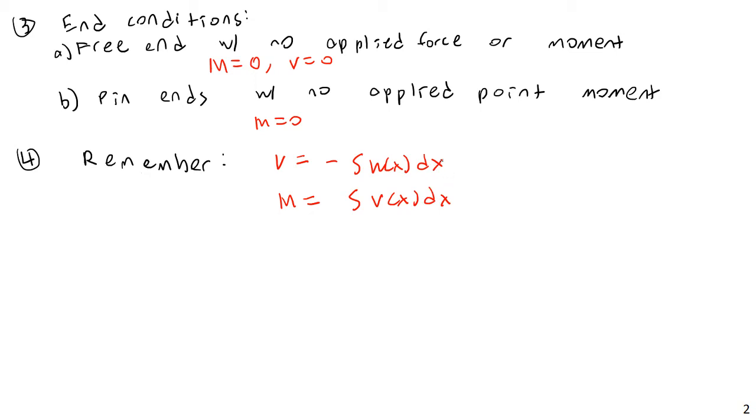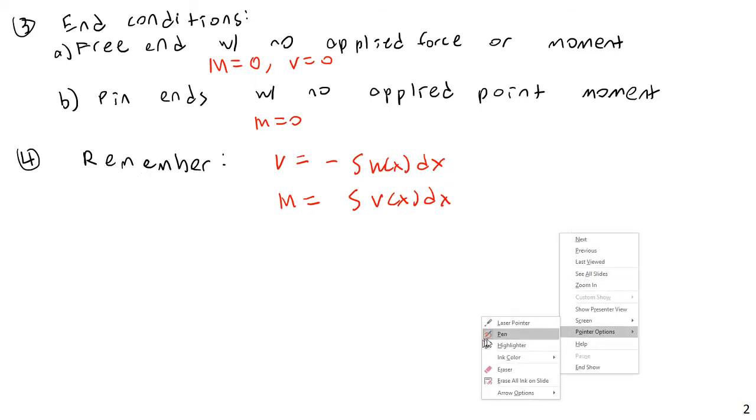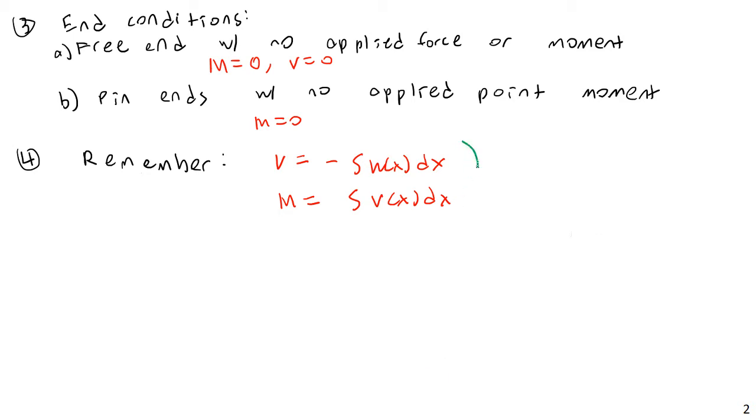Or in other words, what are these? What is an integral? Obviously, the derivative will give you the slope of a line, but fundamentally, these are referring to areas. These are area functions, like most friendly polynomial integrals, functions of x. So in other words, the area under the load diagram gives change in shear.